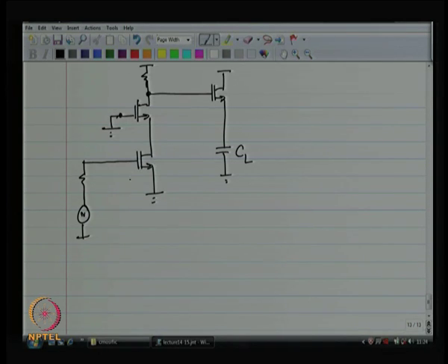The cascode, how it works is, you basically create a change in current. You are applying VGS across this device, you create a change in current. This change in current has nowhere to go but through the drain of the second device, and basically the gain that you see is this change in current times the output impedance looking into the drain of the second device. Now, the output impedance looking into the drain of the second device is going to be what you see looking above, which is that resistor or whatever you have over there, and what you see looking below. What you see looking below is a much larger resistance, right.